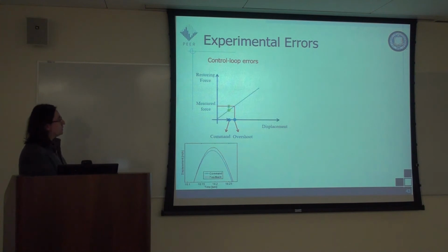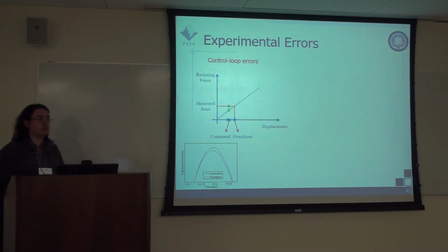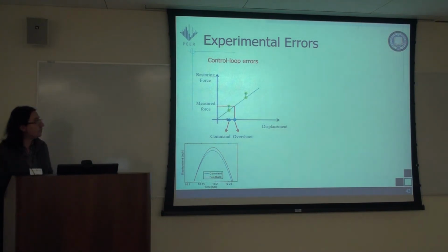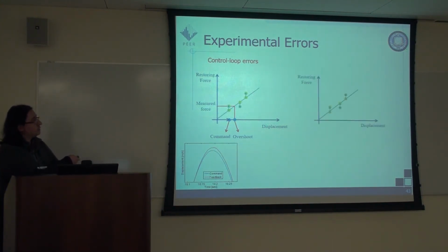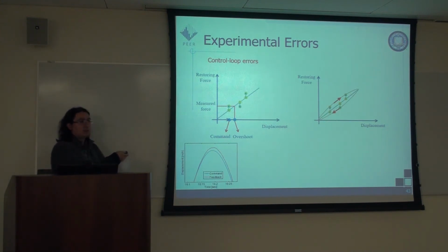So what this does is it moves a point on the diagonal upwards, because now we have a different pair of displacement and force. And then this happens all the way in the loading part. In the unloading portion, any point moves downwards. So when we combine all these points, we obtain a hysteretic loop instead of a line.